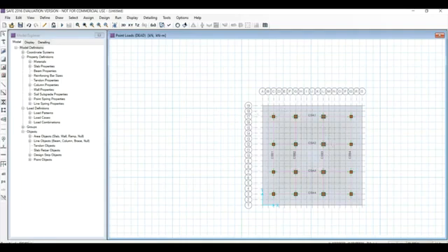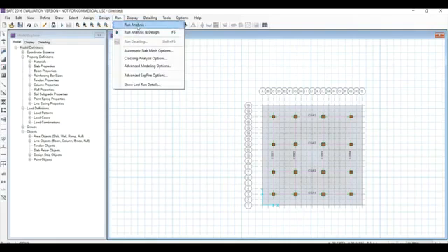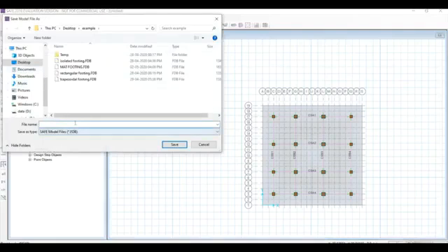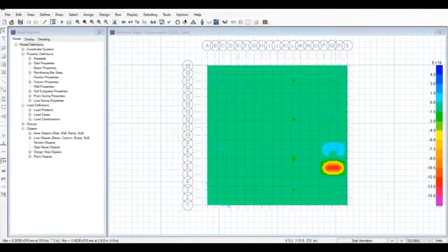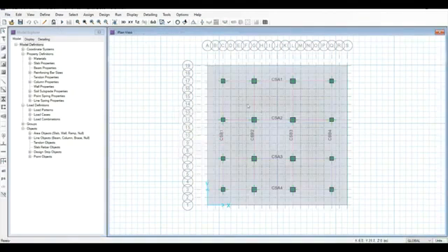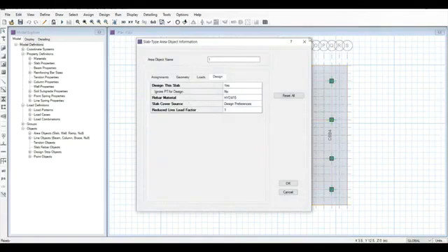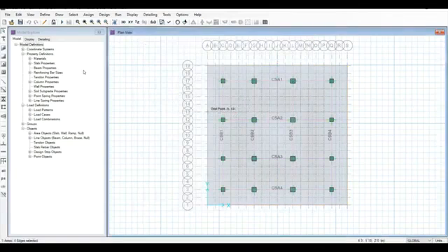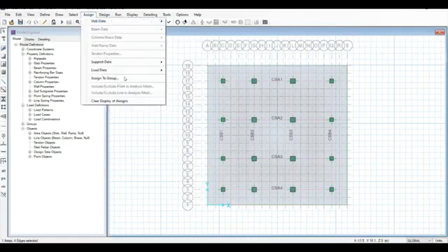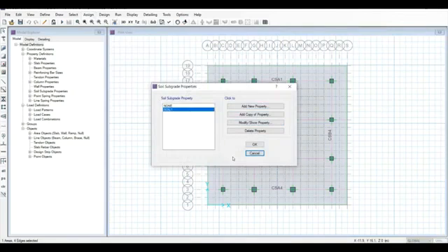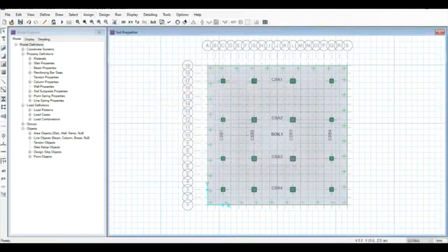Now all the loads have been assigned. Now just run the analysis. Run analysis. Give the name. As we can see, the design has got some fault, since we have not assigned the soil properties, support conditions. So left click on the footing, one area and four edges are selected and go for assign support data, soil properties, and as we have already given the soil one properties, click OK. Soil properties are also given. Then run analysis.